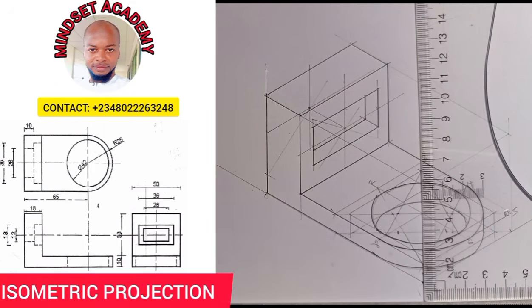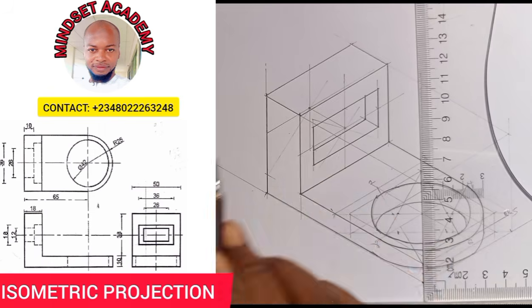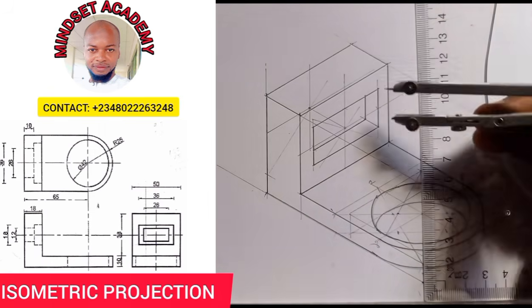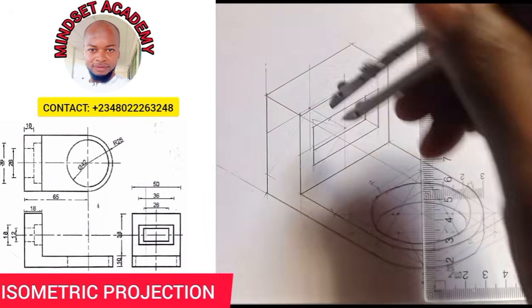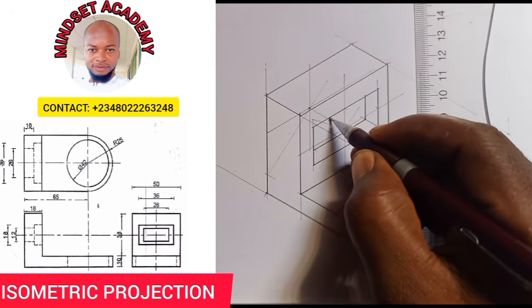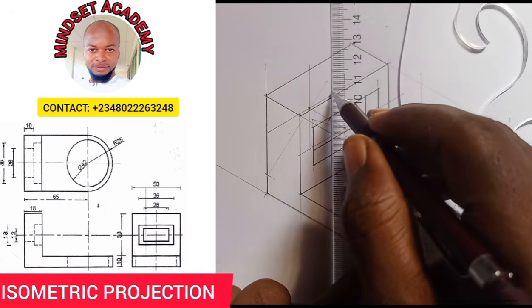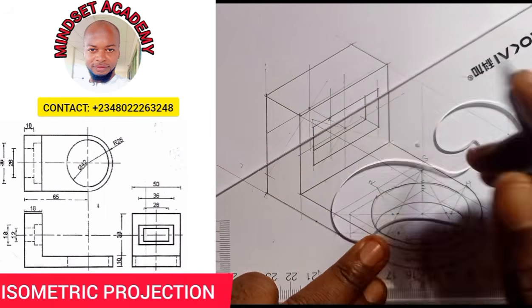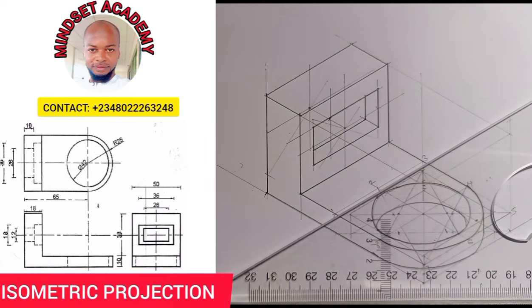right? Then there's another one inside that starts from in. So if you recall, from this line here now, we have the same figure here. So from here, also measure the 8 backward. Know that from here to here is 8. So I'll measure 8 here too. So the 8 here, that is where I want to do the next thing I want to do. Draw your vertical line. I will have the horizontal line already, right? So what is the length of it? If you look at it, it's given to be 26. So I'm going to take 13 each from that 26.